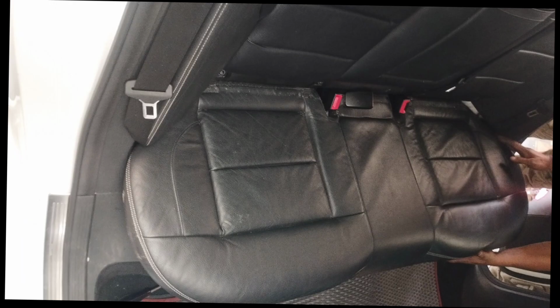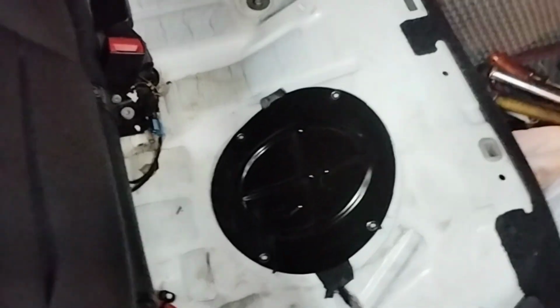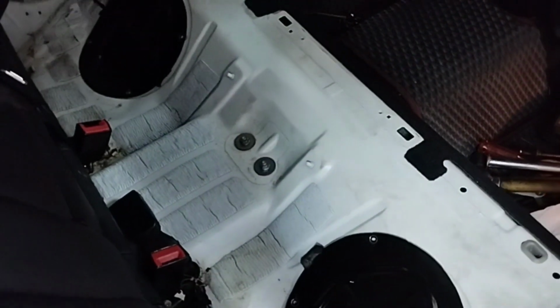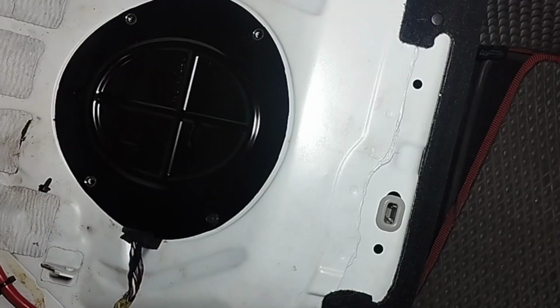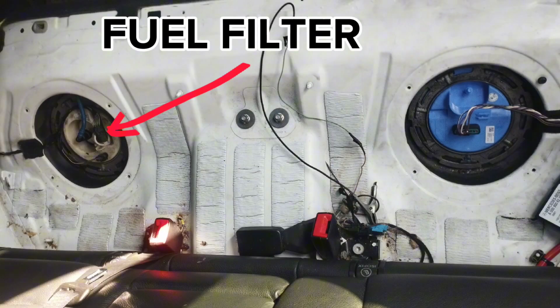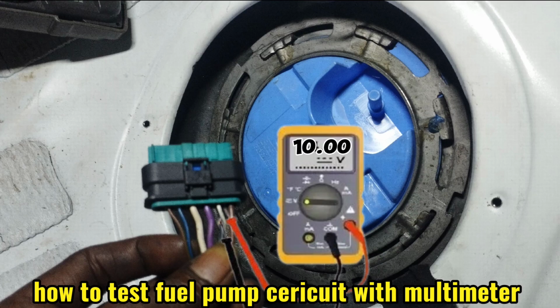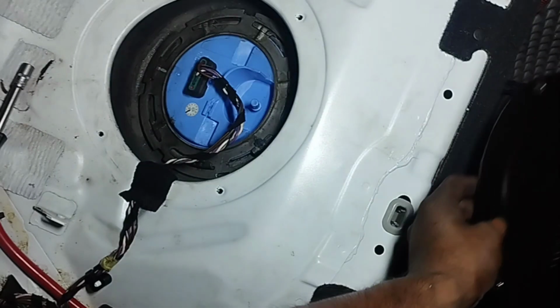The fuel pump is located under the rear seat, so open the seat. After opening the back seat, two black covers are attached with screws. After removing the covers and screws, you will see the fuel filter on the left side and the fuel pump on the right side. How to test the fuel pump circuit with a multimeter.